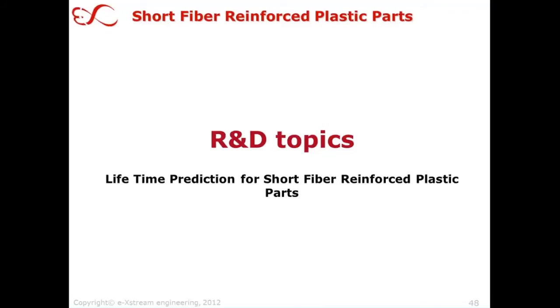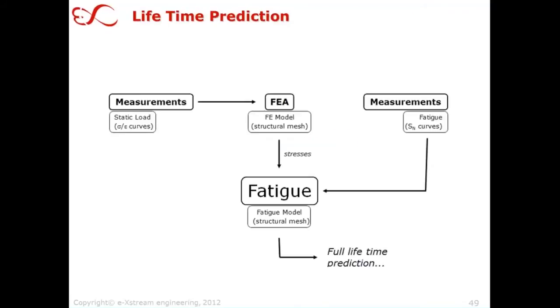So lifetime prediction, of course, is a very hot topic if you look on the market, and if we take the classical approach to it, what you basically do is you have some stress strain curves, so stiffness measurement of your material properties on one side, so this is on the left side of the slide, and for the fatigue properties, it's in some Wöhler type of measurement, so SN curves are measured, and both types of measurements go into simulation software. So stiffness goes into the prediction of the stresses using some standard FEA solver. So it's linear elastic computation used here.